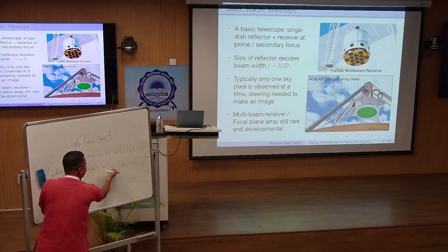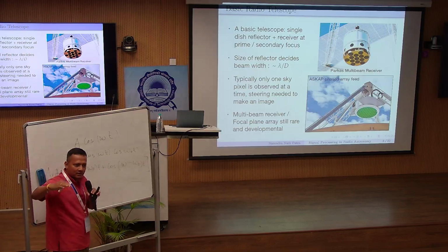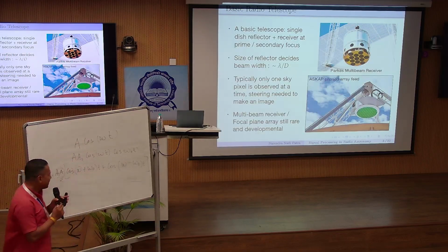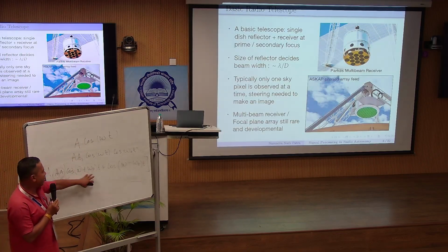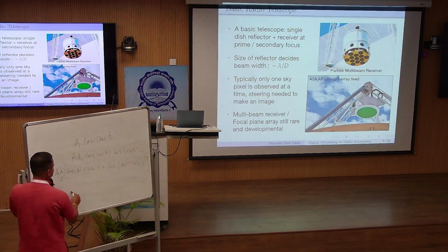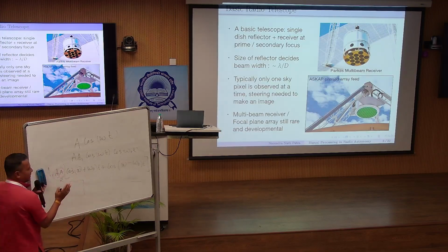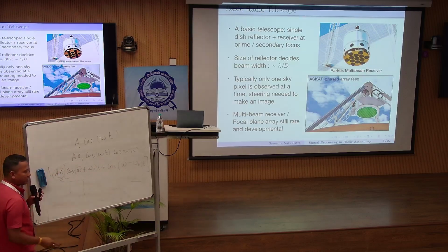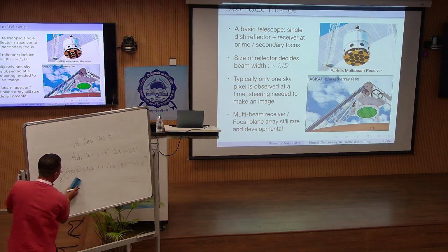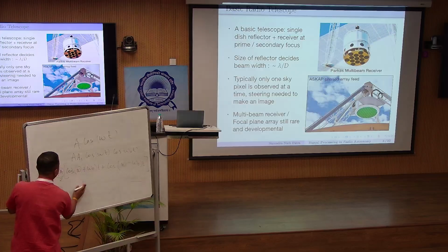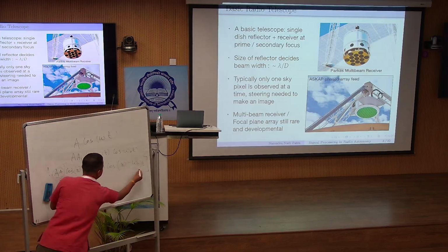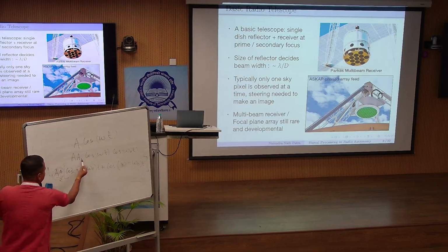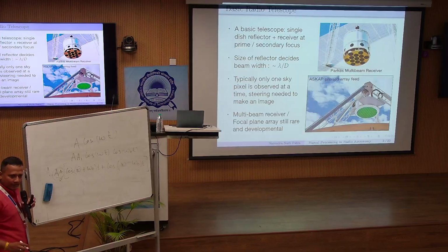This is just a sinusoid, right? So effectively, somehow if I place a low pass filter, a filter which can attenuate this high frequency part, it will only pass low frequency, that is this, correct? And this part it will attenuate, right?